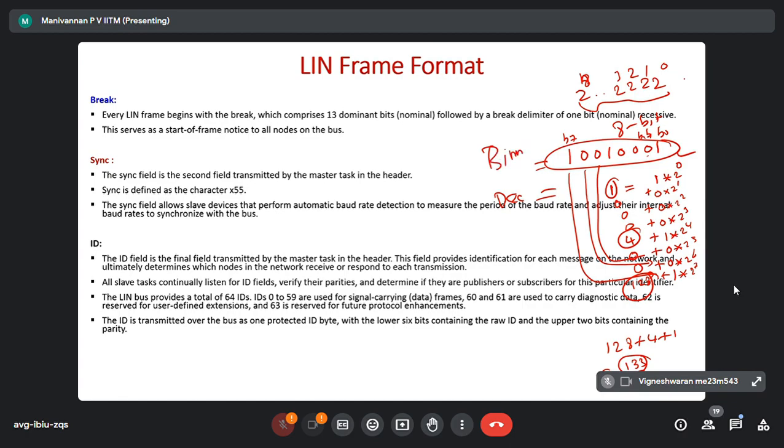Decimal number, you know, correct? Now, hexadecimal means you take a binary number. I have an 8-bit binary number 1011 0110. This is an 8-bit binary number, correct? This is B0, B1, this is B7. I divide the 8 bits into 2 nibbles. I told you 4 bits are called a nibble, correct? Two nibbles. So each nibble, the 4 bits, can be represented as a hexadecimal number.